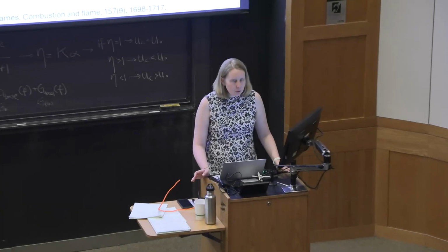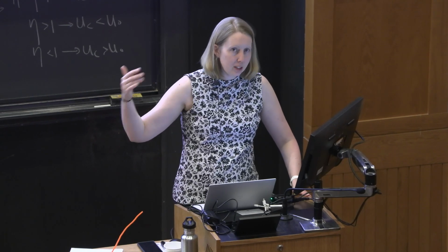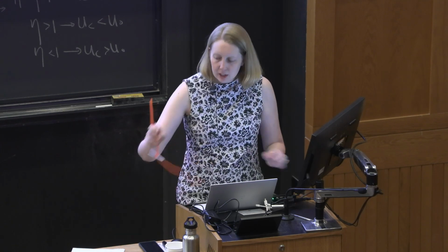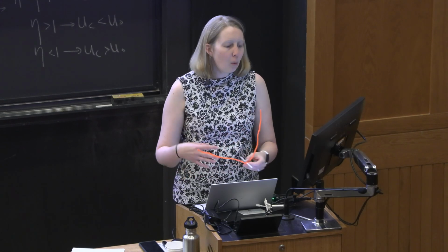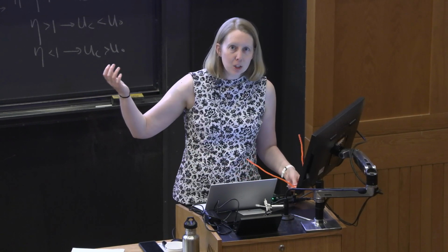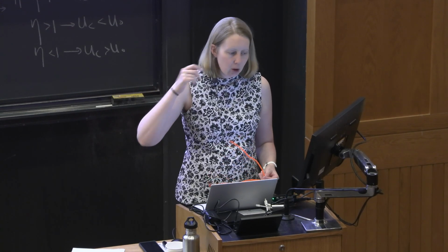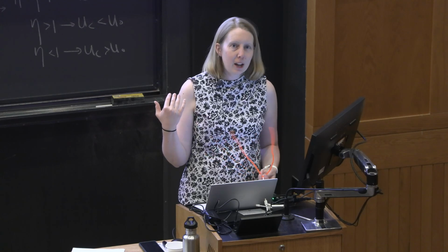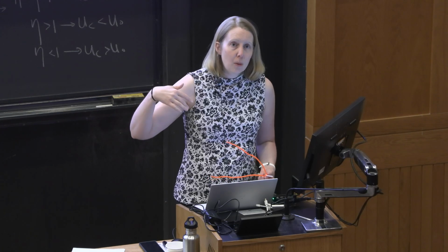If you're trying to measure a flame transfer function, you want to stay in the linear regime, which is like 5%, right? So u prime over u bulk would be 0.05. We've talked about nonlinearities that come from the kinematic restoration and the kinematics of flames. But then there's a whole bunch of other really cool nonlinear behavior that happens when you have complicated flow fields. In particular, there are a couple of studies. There was work done by Balachandran in the early 2000s and by one of my academic siblings, Ben Bellows, who just saw super weird nonlinear behavior in swirling flows that has to do with the dynamics of the flow, not so much the dynamics of the flame.